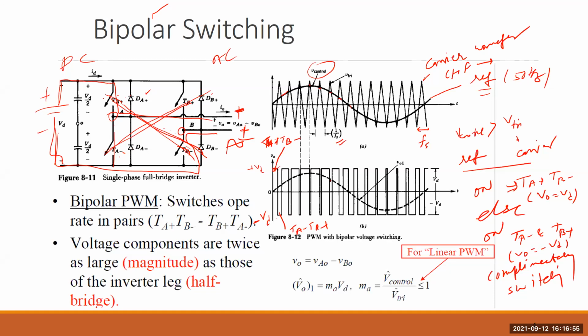So you are generating a bipolar waveform, plus minus plus minus plus minus. Although your target is to develop a unipolar waveform at a time, either all positive or all negative, you are generating a positive and negative bipolar waveform like this.